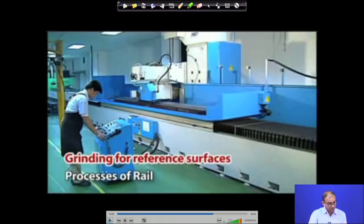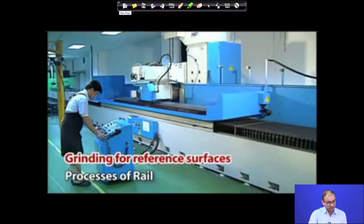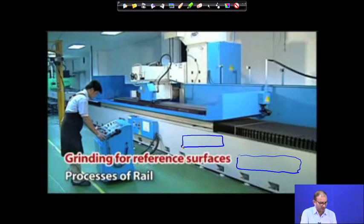Then after straightening you have to create a reference surface here. Now, what does it mean? Consider that you have one block with a very odd shape. This is the surface. Your objective is to create a perfect rectangle out of this. So, what we generally do is first a machining operation to remove this layer, and then a grinding operation. Once grinding is over, you have to mount this thing upside down.